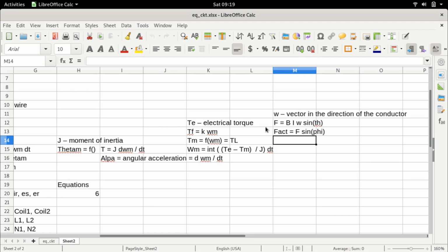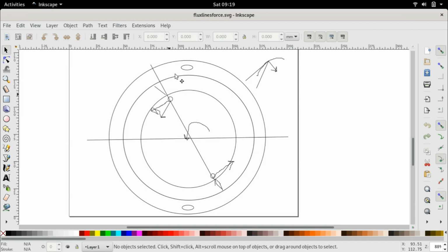Now, for the specific case of an induction motor, and if we are considering the ideal case, not the non-ideal case. Okay? Right now we are looking at the ideal case, and if we say that in the ideal case, the magnetic lines of force will flow through the path of least reluctance along the radius, in that case we can safely say that the angle between the magnetic field and this current in the rotor conductor is going to be 90 degrees. Right? And this is simply because this rotor conductor, this is a cross section, and this rotor conductor is actually passing through the screen.